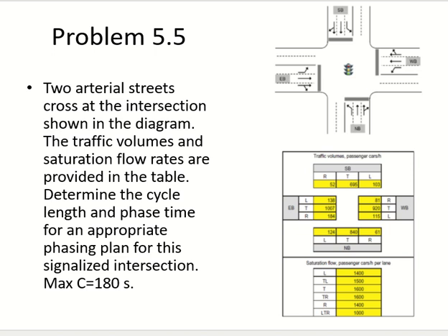For 1 lane it is 50,000. The numbers are given. But right now we have the case for 2 lanes. You can see in all directions I have the same lanes, right? So in all directions I will do left turning multiplied by opposite through, and the number should be less than 90,000. If it is less than 90,000, we make it permitted. If it is 90,000 or more, we make it protected. Clear? So this has been done.